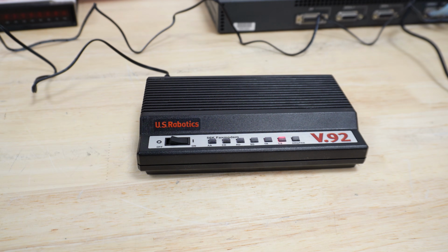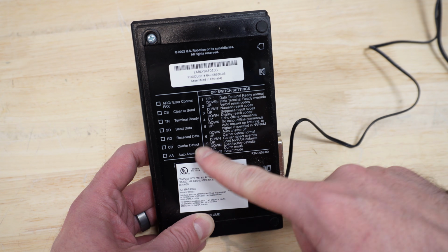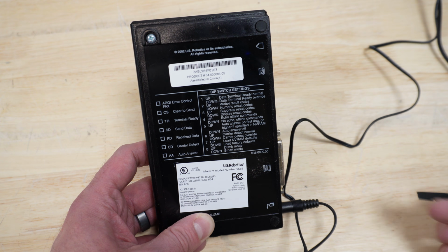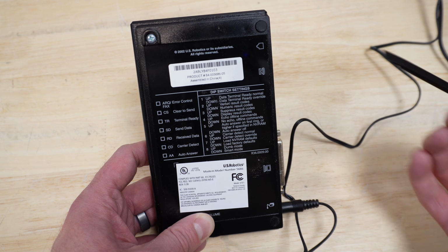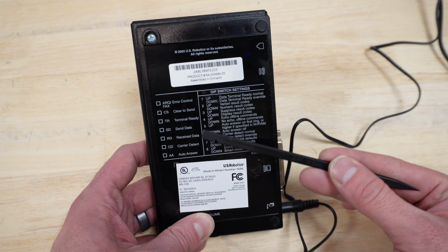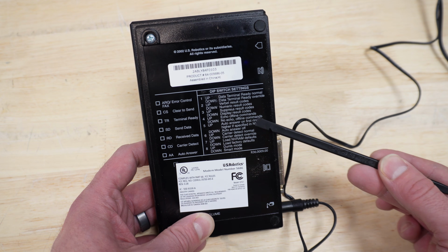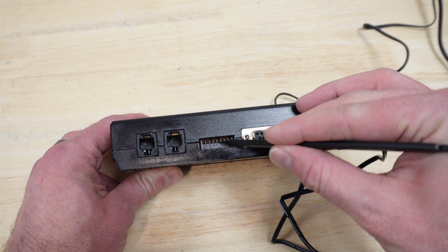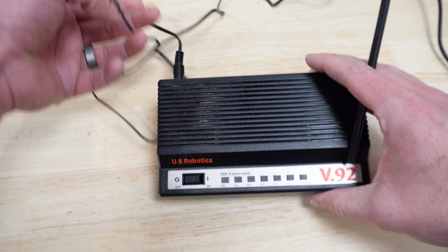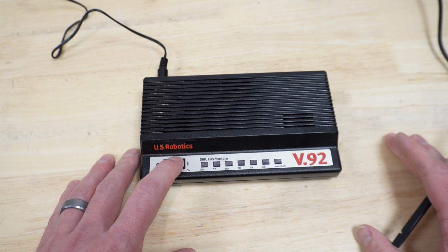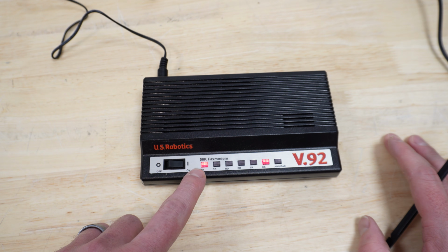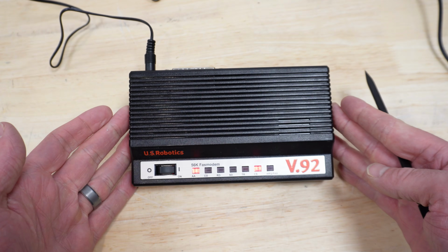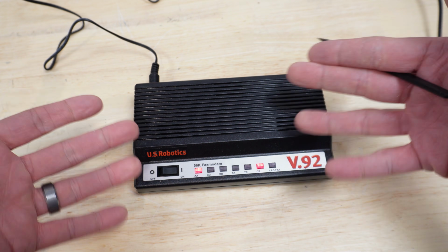That's good. Here's what all the lights on the front mean, and here are the dip switch settings I keep talking about. And I want this thing to auto answer because I'm dialing into it, and that is dip switch 5. It needs to be up, and down in there you can see the labeled dip switches. Let's switch 5 up, and I don't know if we turn it back on. Yeah, auto answer is illuminated now. That's good. I think these things should be just smart enough to understand what they're connected to.